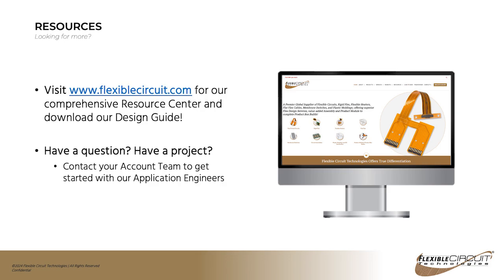If you're using the LCP to seal your circuit, I would recommend using Teflon instead, because we can get Teflon that has a treatment on it that allows us to use a thermal setting adhesive to bond it on. So I would try and steer away from LCP whenever possible, because even the manufacturers of the LCP will tell you that it's a real bear to work with. Anything that's difficult to work with typically equals lower yields and therefore higher cost.